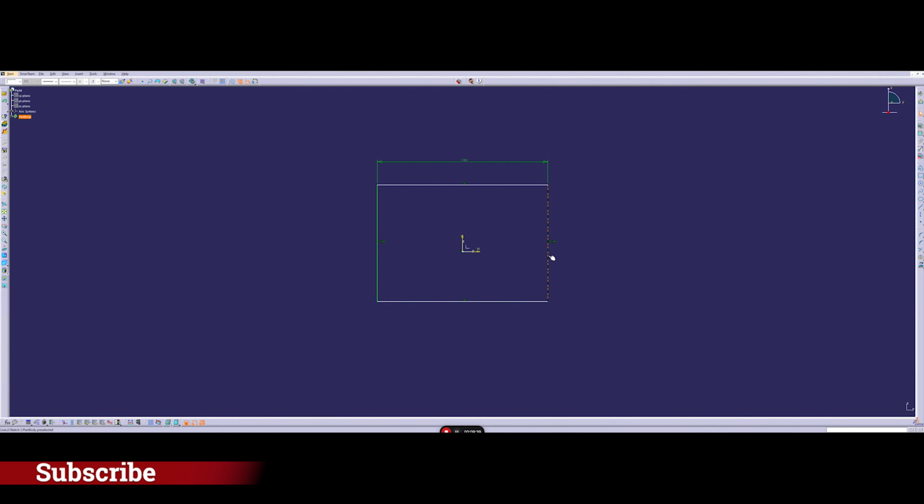Whatever I do, I cannot move it to the horizontal axis, but only to the vertical axis. I can go only up and down. I cannot go left or right because I have a symmetric command from my part to the origin of the axis system.